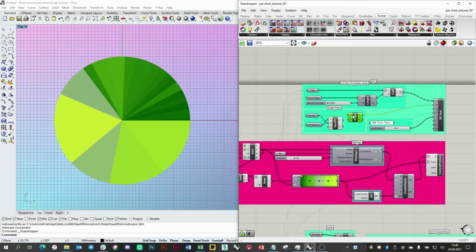Then we take the position, which are these points, and straighten their direction. So this is actually not a point, but a plane to give into this position parameter. So the position parameter always takes not only the point, but also the orientation of where this text should direct, and align this with the vector pointing away from the center and put that into the position input.